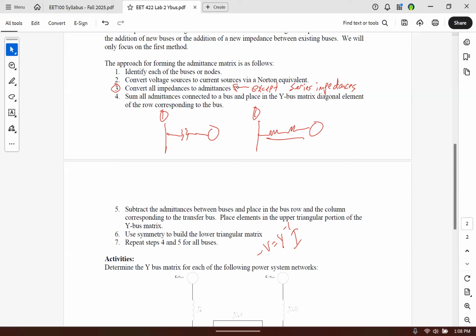But a computer doesn't have the ability to interpret that. So what these power system programs do is insert a bus between there. They'll actually put a dummy bus between the transformer and the generator. So even though you say I've got a 5-bus system, they're actually putting in buses all throughout the system when you're interconnecting two different impedance devices. The reason I'm telling you that is because when I used a different program, called Power Tools for Windows, it would pick up whenever I would try to put what's called a tie line.